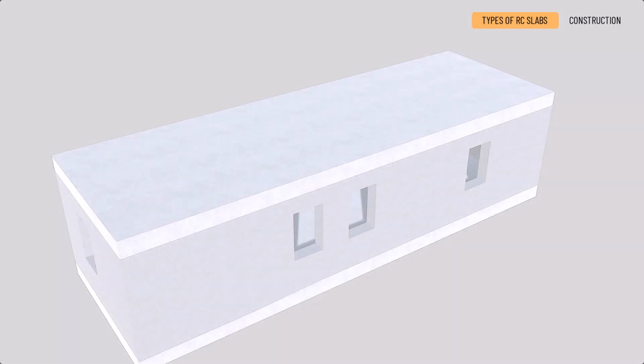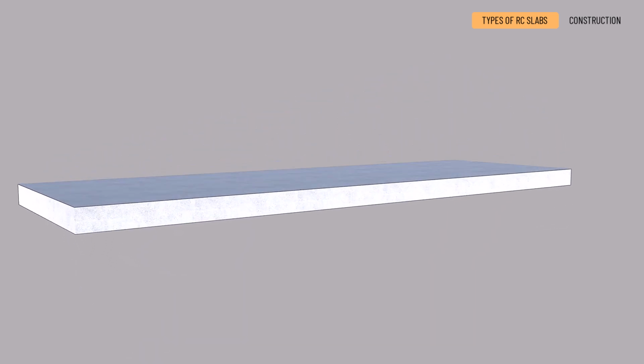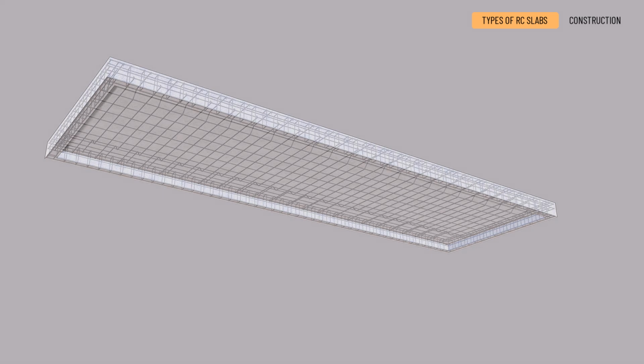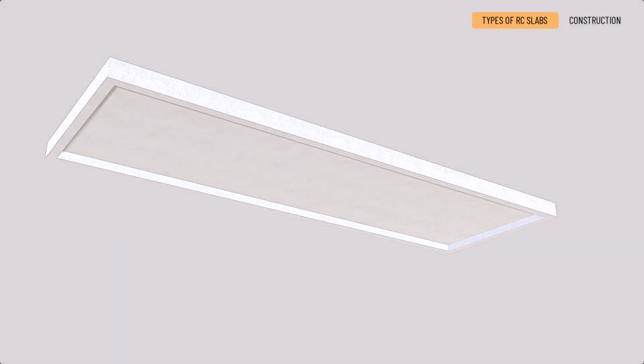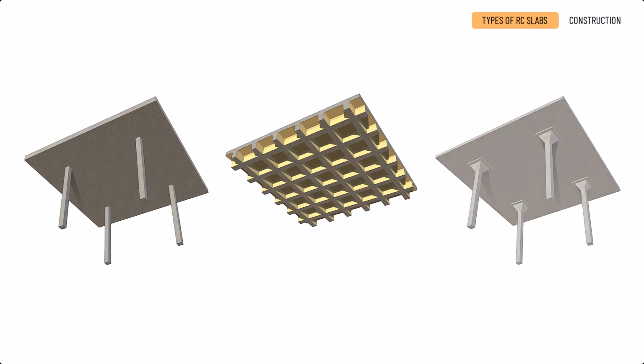Monolithic reinforced concrete slabs are custom-made structures, cast on site, based on detailed structural designs, to ensure that the reinforcement's dimensions and distribution, and also the slab's thickness, meet the required load-bearing requirements at all points. Monolithic reinforced concrete slabs may be flat slabs, ribbed, upstand or downstand, coffered at the top, or two-way slabs.